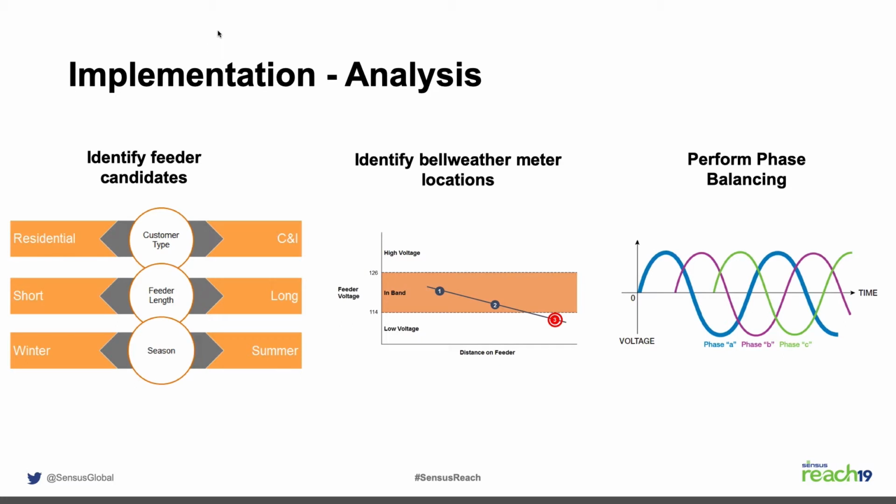A consultant was speaking, I think at Tech Advantage last year, and we hadn't thought of this yet, but they did an analysis like this, and at first they got the results back and they go, well, that feeder is not qualified for CVR because of the highs and lows between your A phase and your C phase and the type of equipment. They didn't have single phase. It was all or nothing.